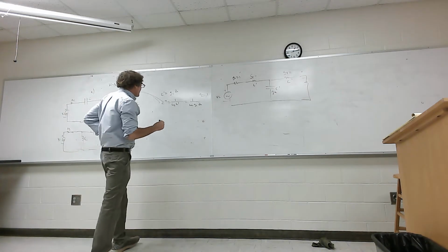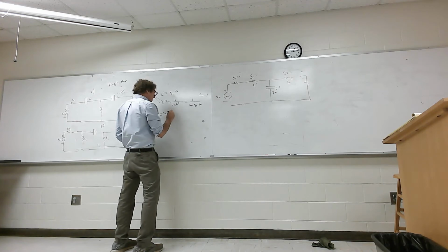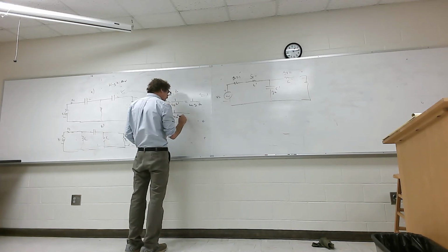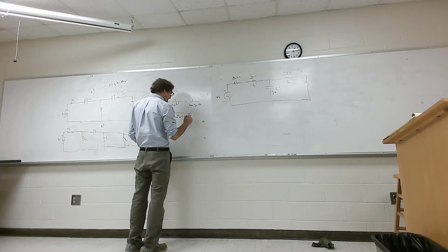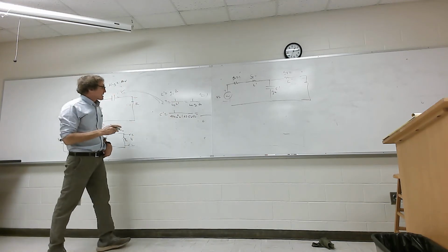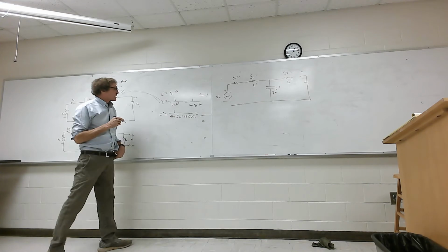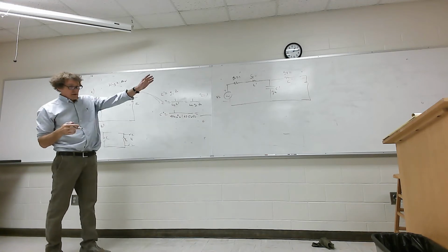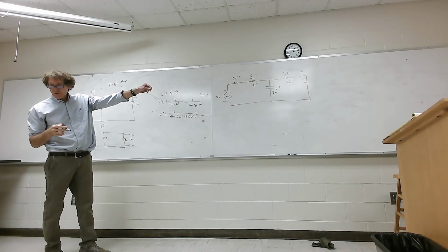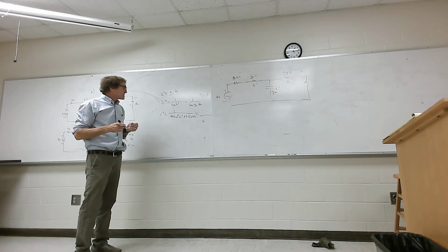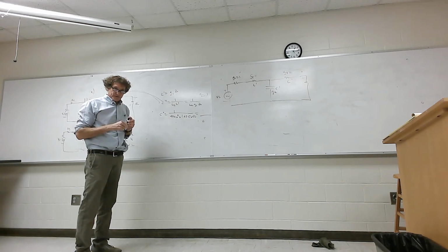So if you take a look at that, what is that value? Well, it's 1 over 4 pi times 10 to the 9, times G1, which was, what was it, 1.0315, and then it's times 50. So, can anybody give me that value? And that's actually C double prime. Remember, high pass, you still get the values for L prime and C prime, and then you use those to get the actual values of the dual component by doing this little trick. 1 over omega C L prime to get C double prime, the actual capacitance. Anybody?